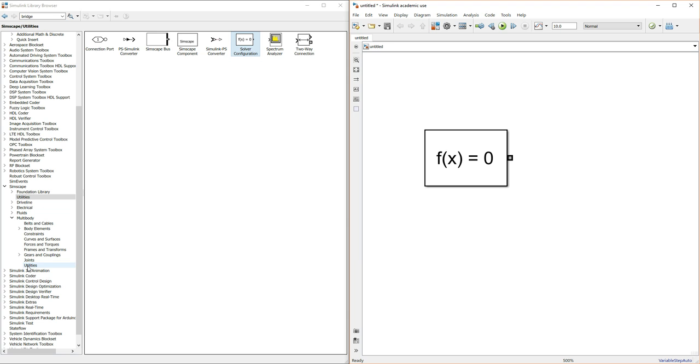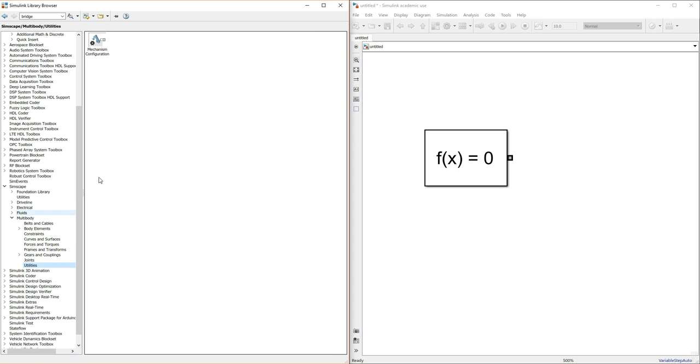So now we've got this. What we now need is, if I come down, see I'm entering multibody, drop all the way down, get to Utilities. In Utilities, if you remember, we need something that will define our relative tolerances when we're solving. We need something that will give us orientation of gravity, where gravity will sit.